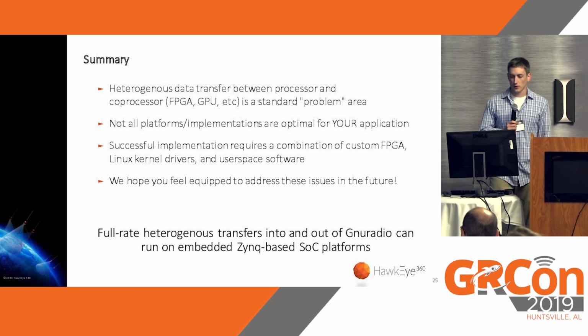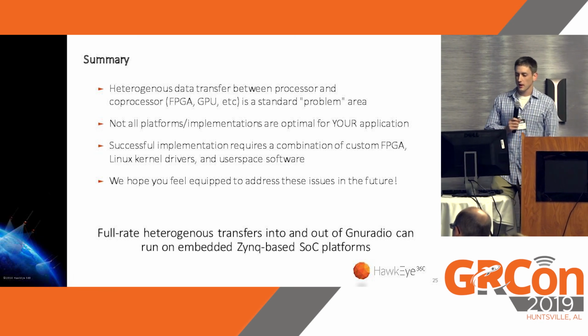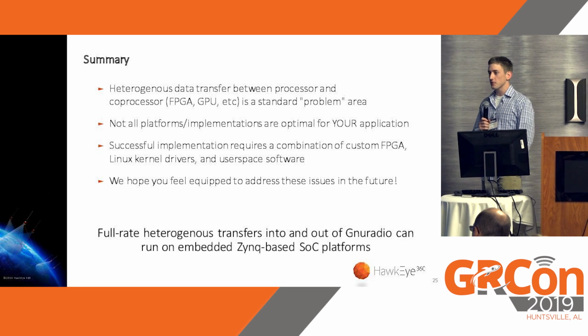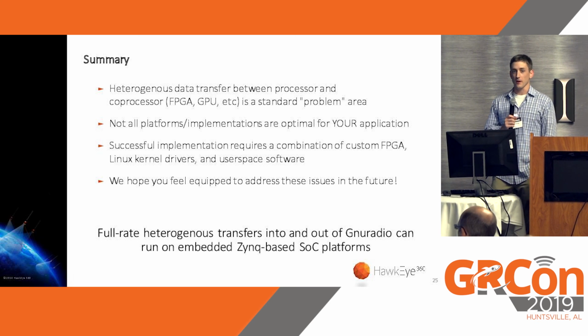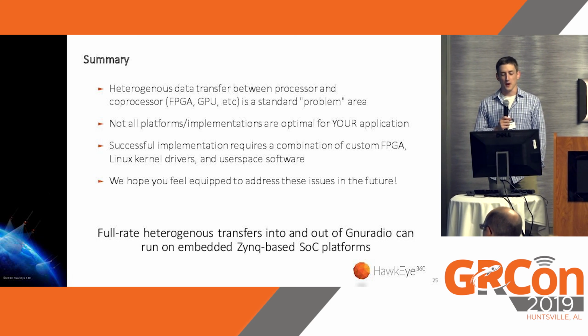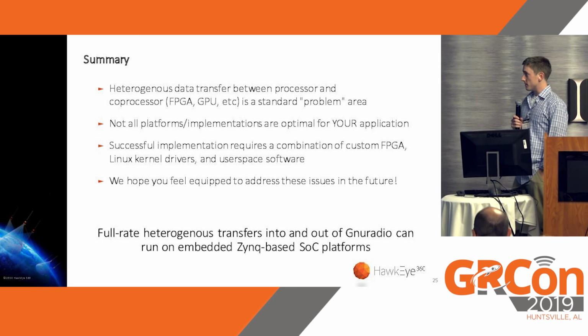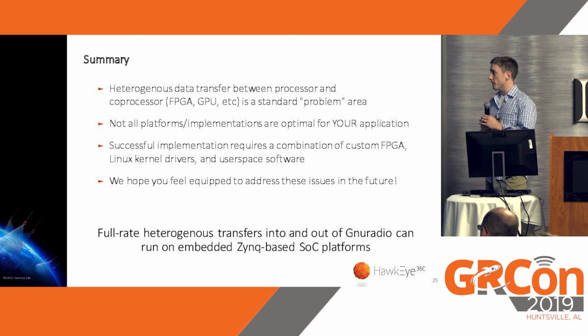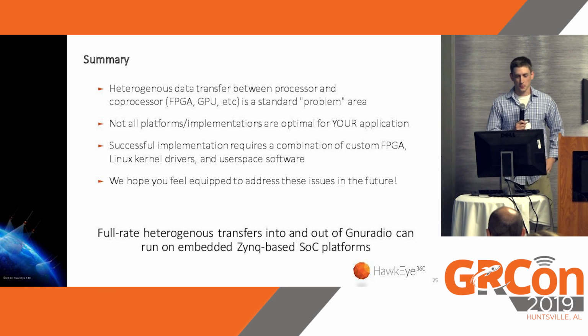All right, so at the end of this, I hope that I've provided enough of a crash course for you to feel equipped to address these issues, or at least understand what some of these things are doing behind the scenes, if they are or are not living up to the expectations that you have. And I also want to emphasize that full rate heterogeneous transfers into and out of GNU Radio are possible on embedded Zynqs. I hope this can inspire more people to look into that.